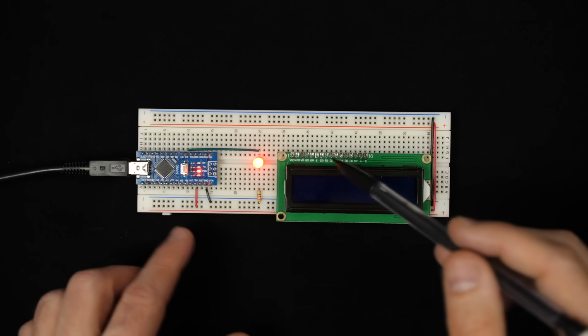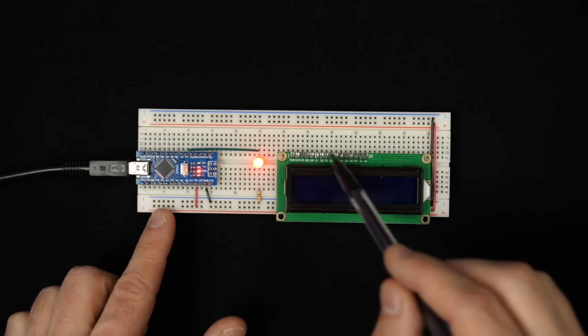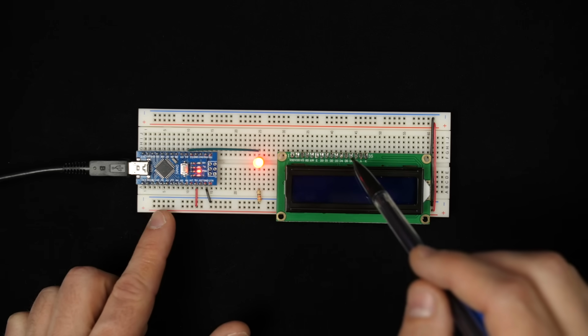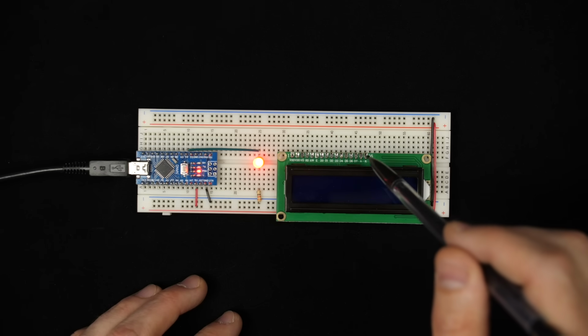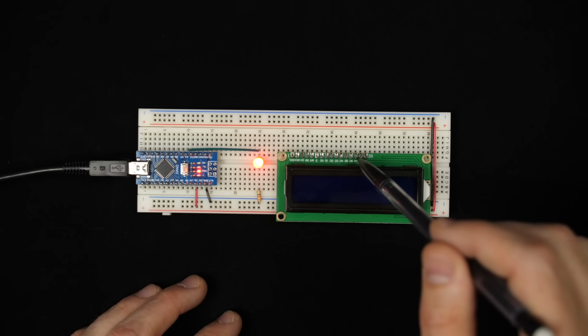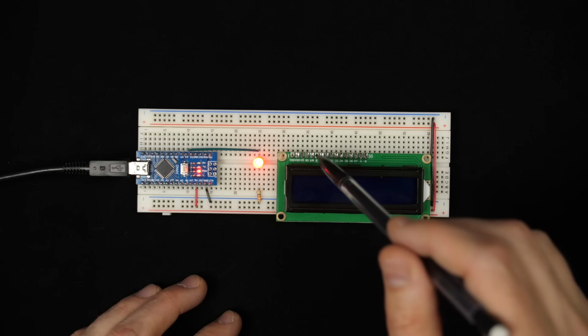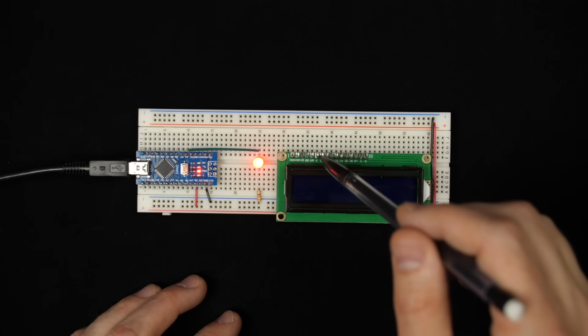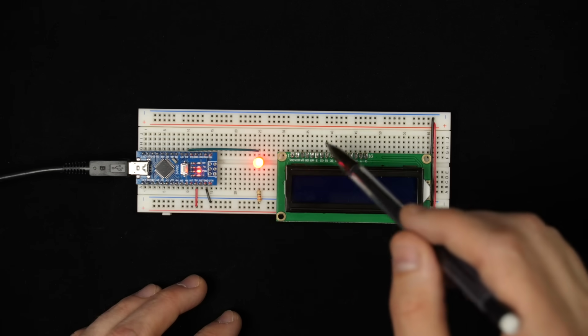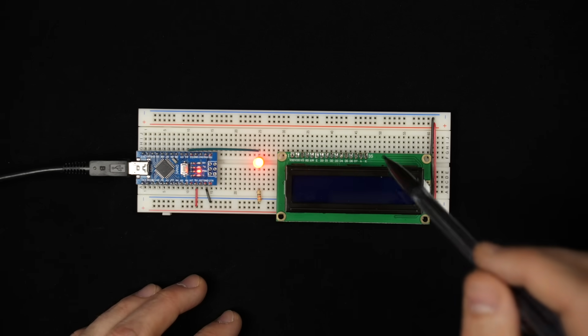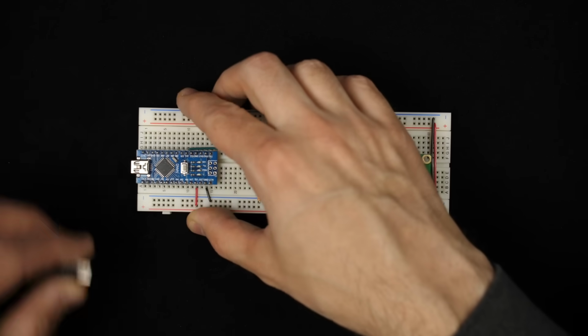And the way this LCD works, it's pretty easy to interface with the Arduino. There's a bunch of pins that you can connect here, but if you're not doing anything fancy with the LCD, which we're not planning to do, we just need to connect pins D4, D5, D6, and D7, just 4 of the data pins. And then there's the RS pin, the register select pin, and the enable pin. I think those are the only 6 pins that we need to connect to the Arduino. And then there's a few other things we need to hook up, power and things, but we'll go through all that. So I'll start by disconnecting the USB here.